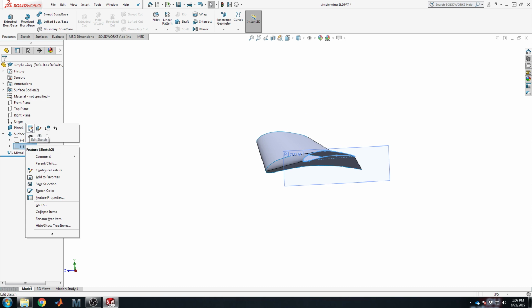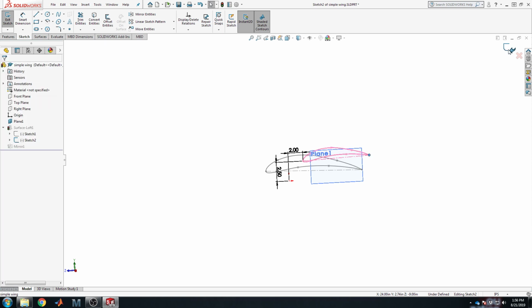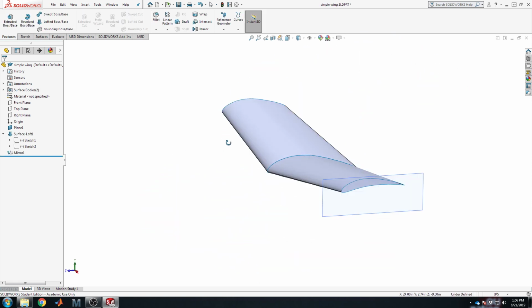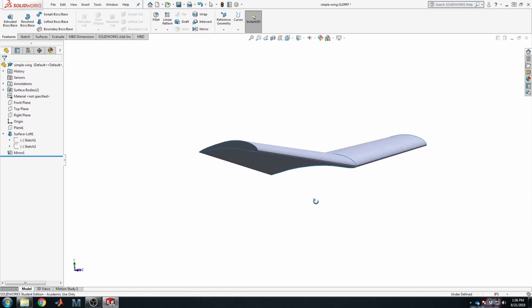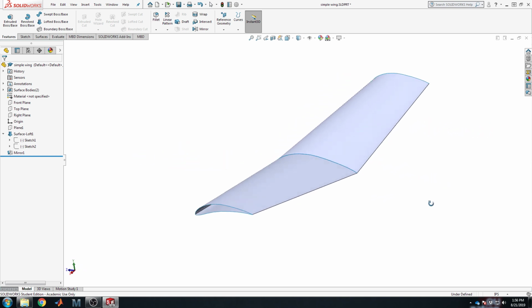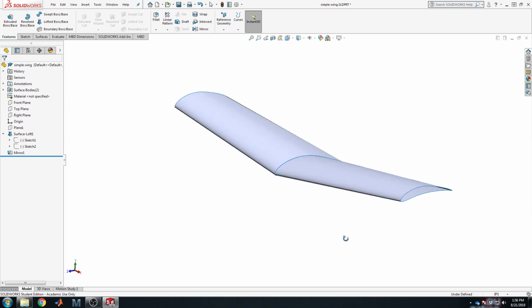If you wanted to go back through and even modify your airfoil, maybe you got the taper ratio a bit wrong, you need more chord out towards the tip, change that to 9 inches, stretches the sketch, escape, escape. Well, look at that. Now the wing's a bit different. So that type of geometry and quick update, hide this plane because it's in the way, is really, really handy for defining aircraft shapes and doing lots of quick conceptual design images and layouts. So really, I like this.